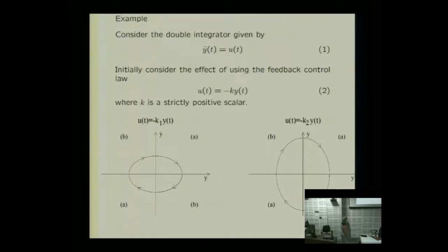And we see why. We use a simple output feedback controller where we're using more than one value of K. So on the left-hand side, we have some value K1. On the right-hand side, we have a portrait corresponding to K2. And we look at that double integrator and we say, well, yes, 2 integrators in the forward path, difficult to stabilize. If I use output feedback, I can't take a point, even in this nominal case, to the origin.